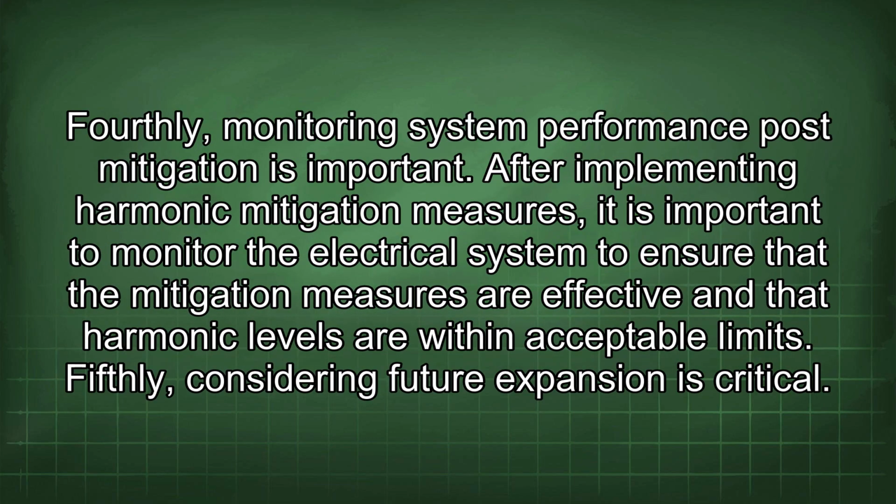Fourthly, monitoring system performance post-mitigation is important. After implementing harmonic mitigation measures, it is important to monitor the electrical system to ensure that the mitigation measures are effective and that harmonic levels are within acceptable limits.